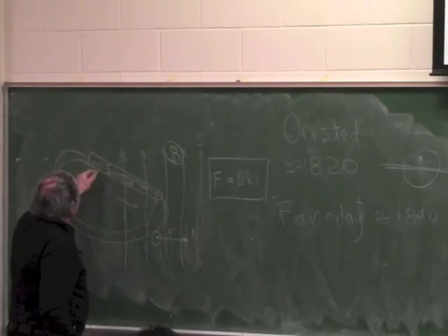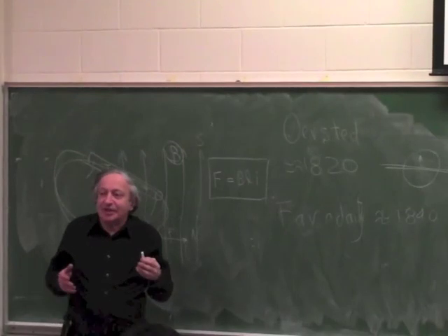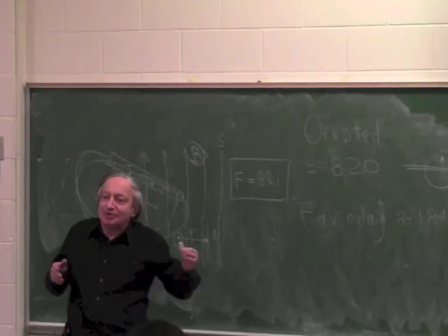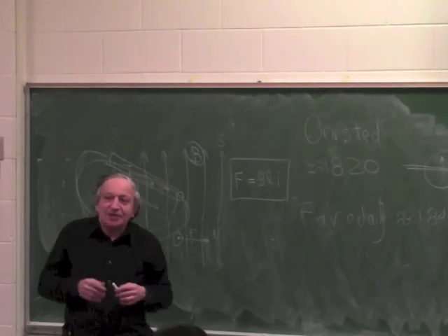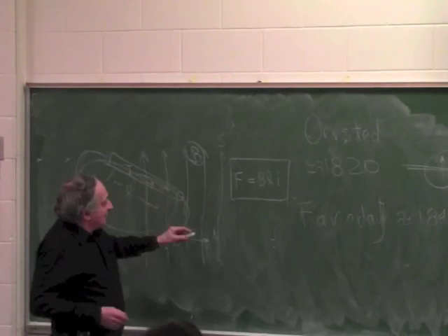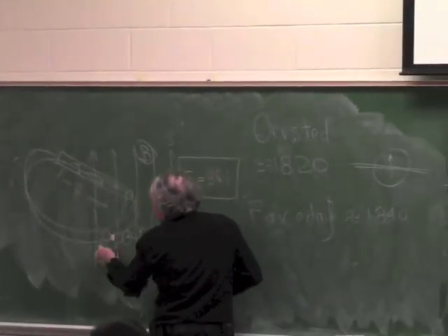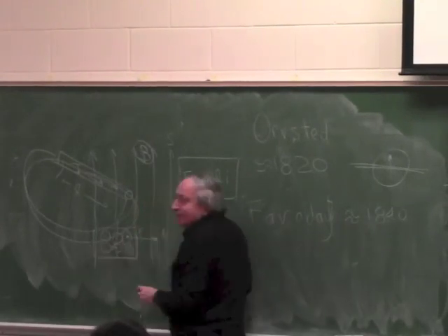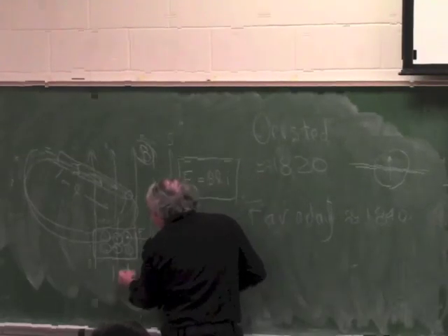So if you wind the wire many times, you are putting many units of L in parallel, right? So you can explain it two ways. Either you can explain it, you're making the effective L longer by putting many units in parallel, or the easier way to understand it intuitively, you're making the current bigger. Because if you wind the coil with many turns, you end up with many currents, and they all appear like one big current equal to Ni.